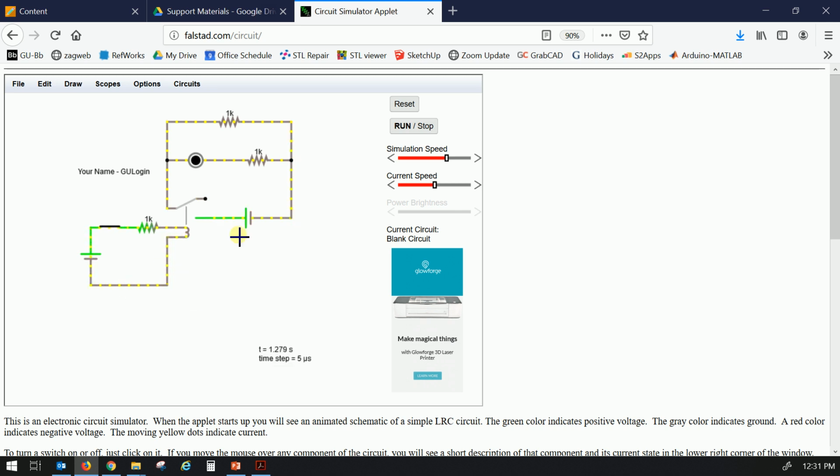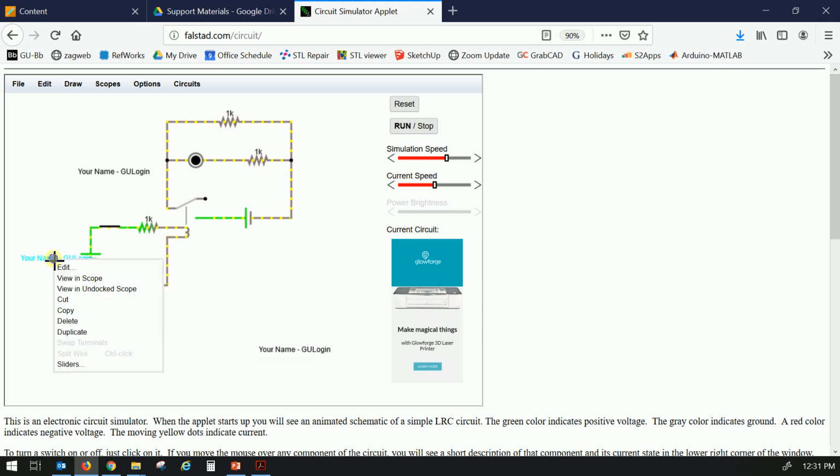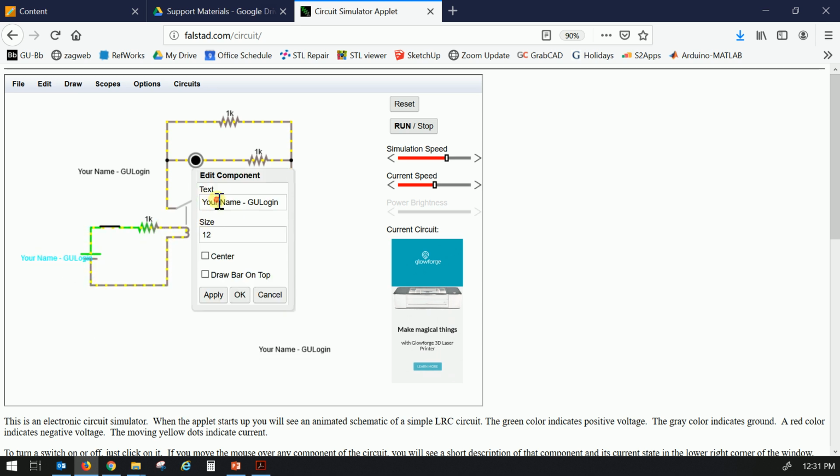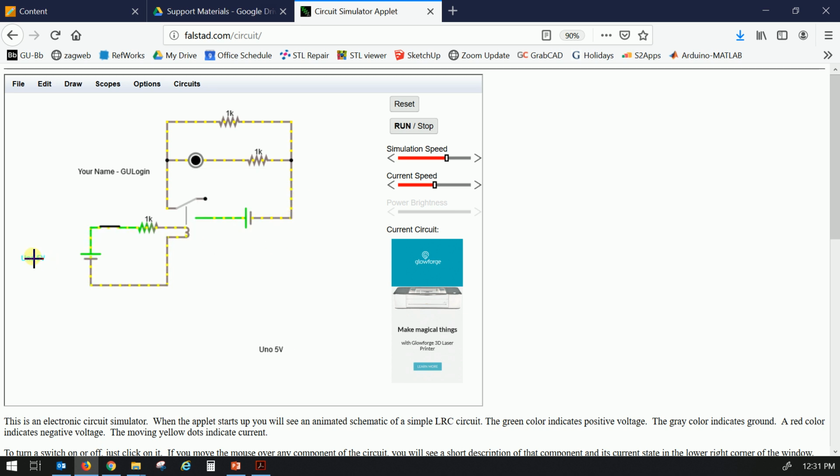All right, so again, we've got our primary circuit and all its components. Let's go ahead and add the labels here. I'm going to select this, paste it. Let's label our important things here. So this is going to be our Uno, and we are going to use the 5-volt supply this week. So that's here. Oops. Control Z to undo that. Space bar allows me to grab and move things. Copy. Let's paste this over here. Again, this is going to be the secondary voltage source.